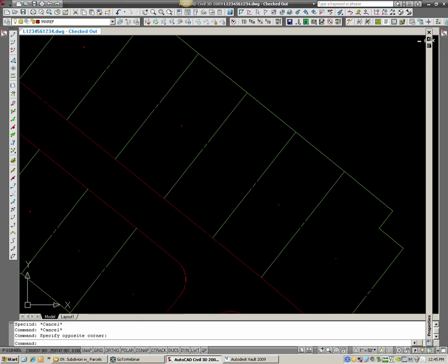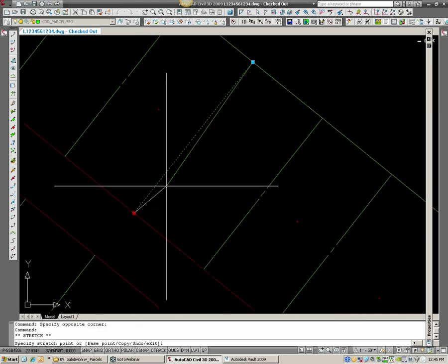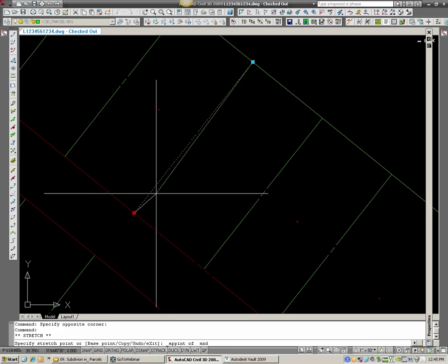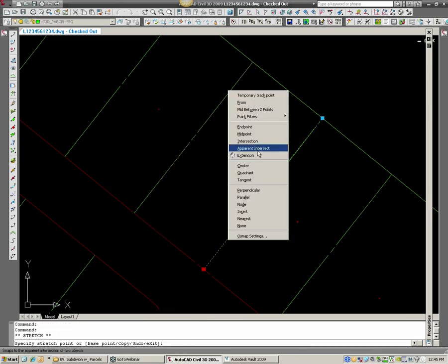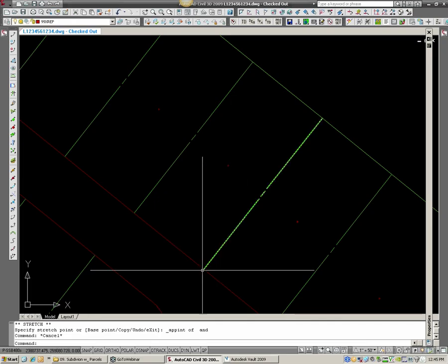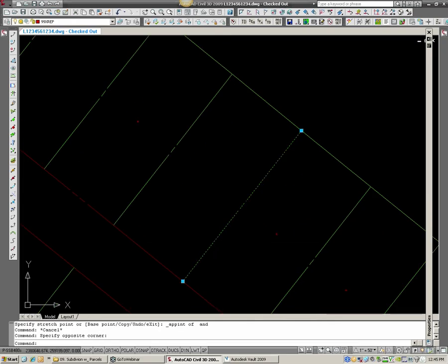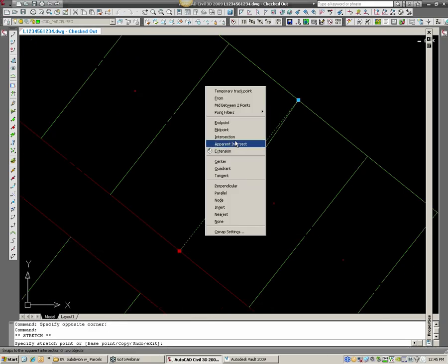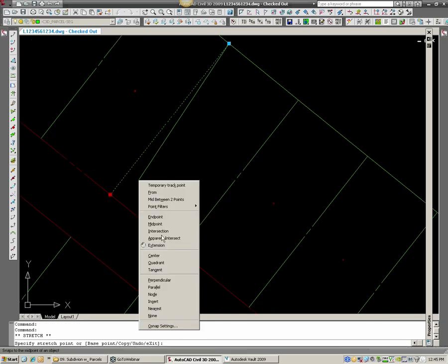So to have these parcels be created, you can see there's no dot there before I exit this file. And if I just bring those to close, you can see there was a gap here. As soon as I filled that gap, this parcel created. Same thing, there's probably a problem with either this line or this line.